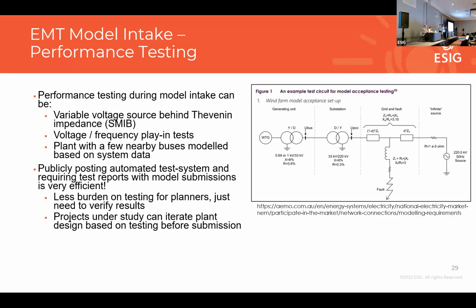That's the fundamental single machine infinite bus representation that we will typically use to test models in. And this is of course very, very simple. There's not anything frequency dependent in the network equivalent. It's typically just a series RL representation.